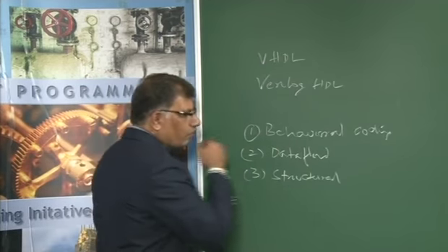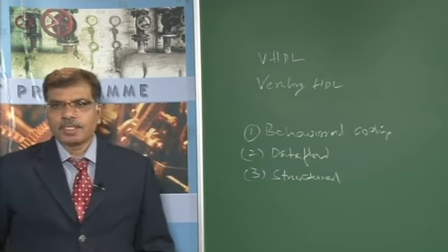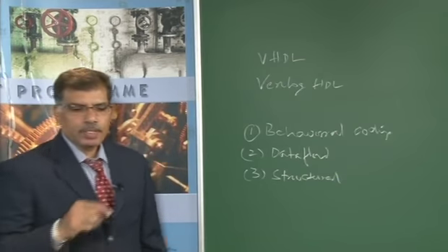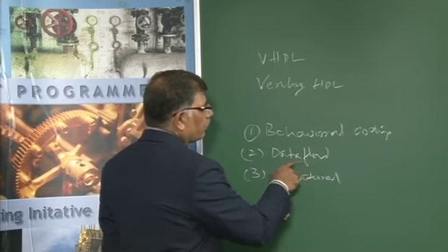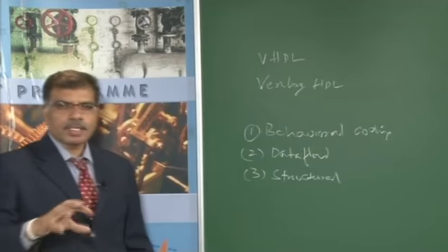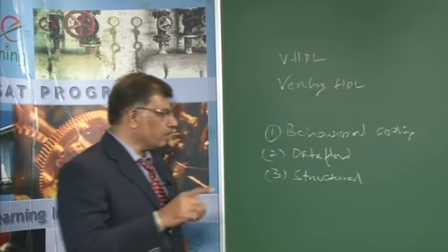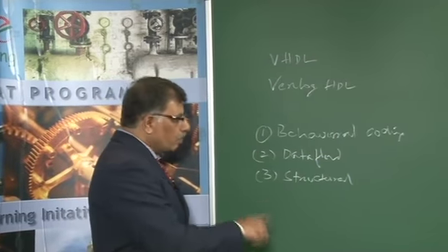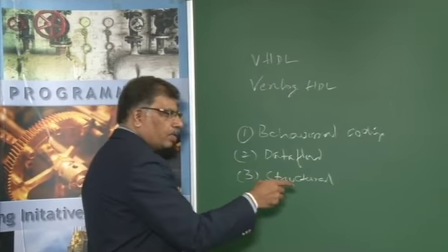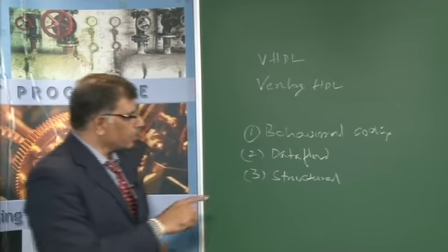In data flow coding, by identifying the truth table of the design you want to build, you can use logical expressions to define it in the language. That is called data flow coding. If you have a circuit diagram with the logical expression, you can write the code by specifying the components within the program itself. That is called structural coding.